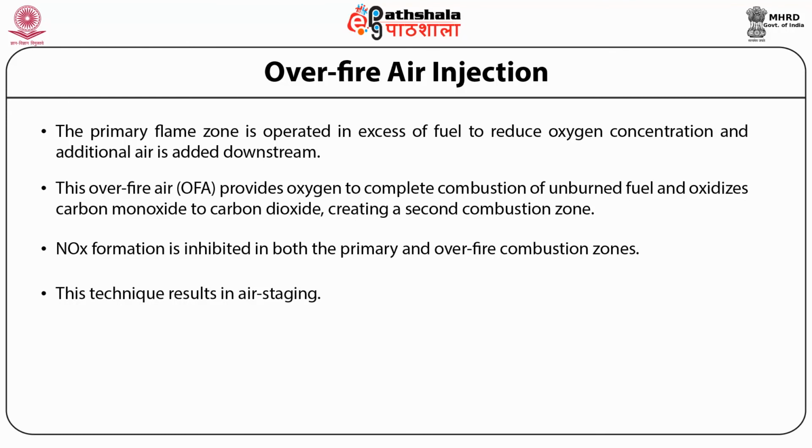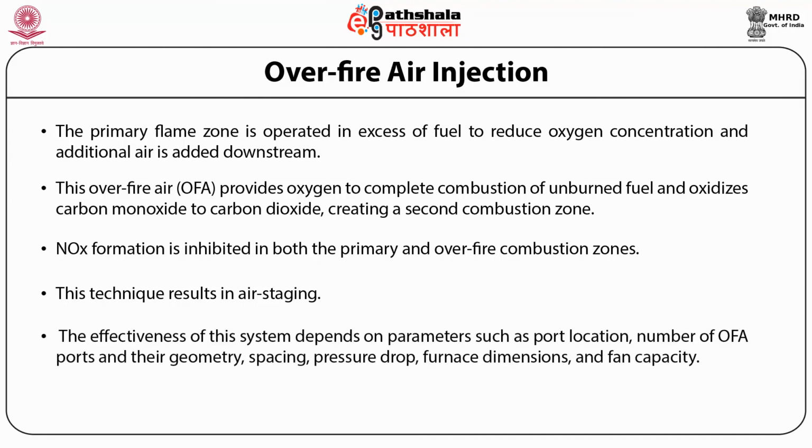Here, 10 to 20% of the total combustion airflow is fed above the flame through OFA injection ports located at the topmost levels of the burner, burning solid fuel such as coal and solid waste. The effectiveness of this system depends on parameters such as port location, number of OFA ports and their geometry, spacing, pressure drop, furnace dimension and fan capacity.